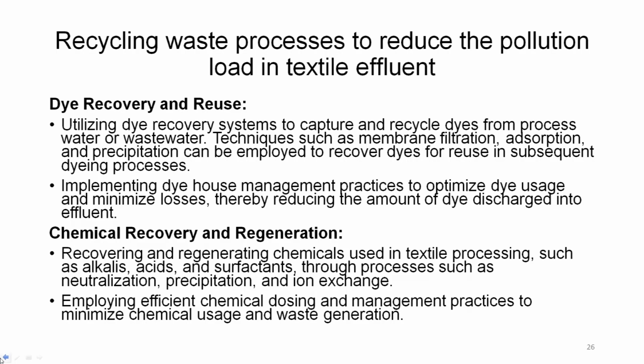Utilizing dye recovery system to capture and recycle dyes from process water and wastewater. If this can be achieved, nothing like it. Techniques such as membrane filtration, adsorption and precipitation can be employed to recover dyes for reuse in subsequent dyeing processes.